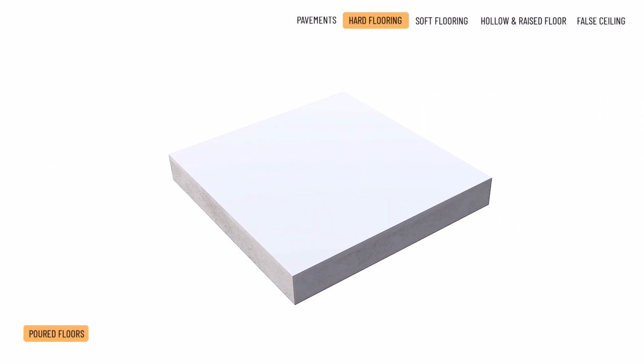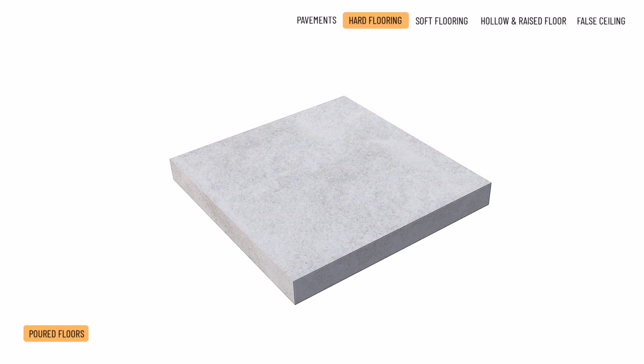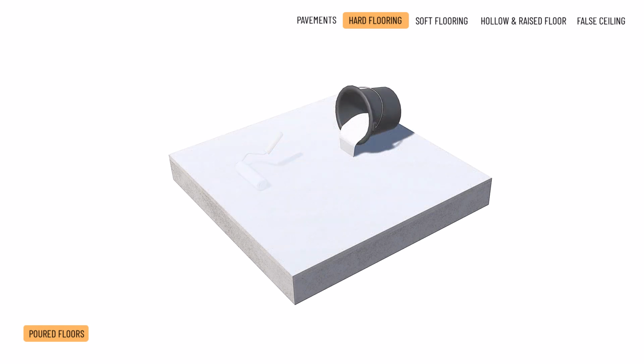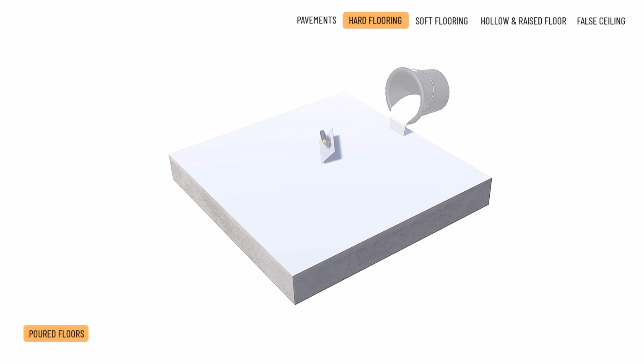Resin-based coatings are thinner, ranging only from 1 mm to 5 to 10 mm. For their application, a precisely levelled or properly evened subfloor is required, on which a system-specific primer must first be used to create an adhesion bridge. After that, the slowly self-levelling coating must be evenly spread with a trowel.